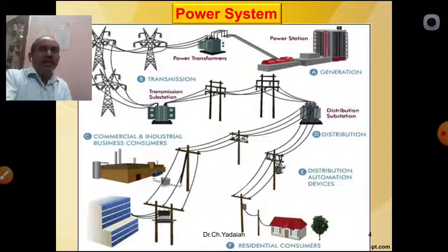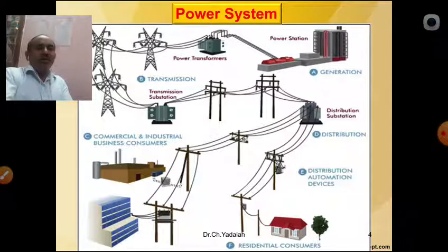Generally we give one feeder directly to the railway department, which takes the 132 kV HT lines. Next, the 132 kV line is stepped down to 33 kV, and the 33 kV line is transmitted to thickly populated areas, where small 33 kV by 11 kV substations are erected in the city.